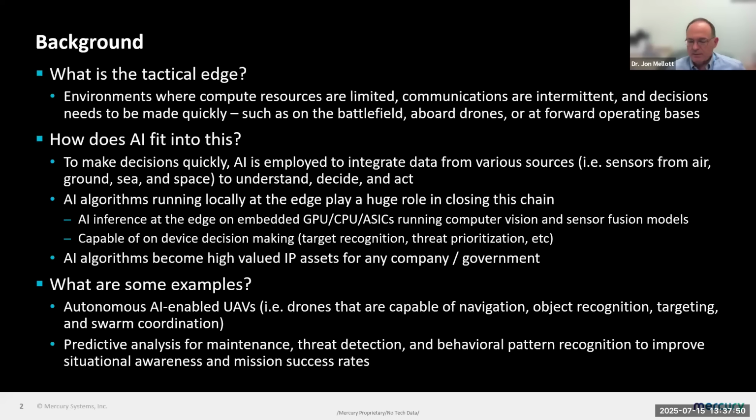The other thing people think about in the supply chain for semiconductors in particular is that they're very focused on the wafer fabrication aspect of it. That's just one piece of it. That wafer gets fabricated, it goes somewhere else for test. It goes somewhere else to get cut up into individual die. It goes yet somewhere else to get packaged. And then those packaged parts likely go somewhere else to get tested.